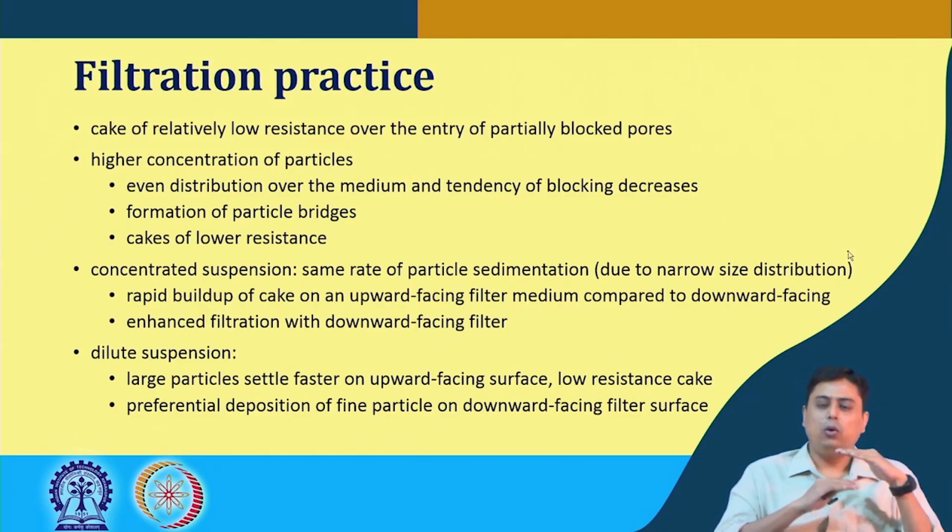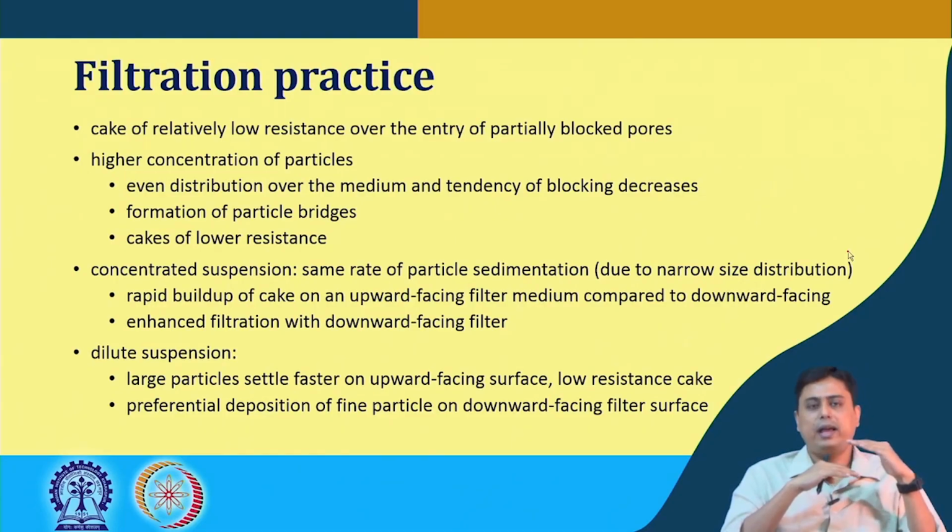In that case only the smaller particles in that narrower range will come closer to the surface and sit on it, and you have an enhanced rate of filtration in the case of a downward facing filter, because here the cake thickness is lower.